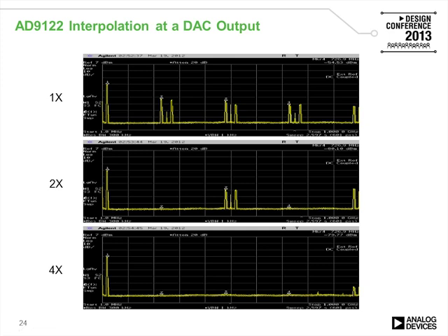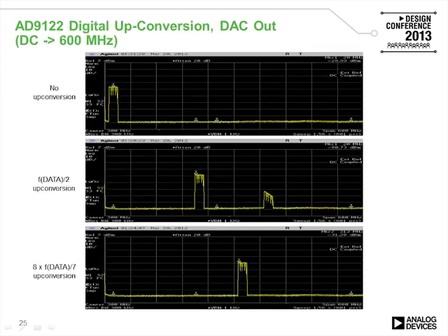One of the benefits of doing this is that our filtering requirements are much sloppier over here when we're doing 4x interpolation as opposed to 1x. If we want to consume this bandwidth right here with 1x interpolation, we would need a much tighter brick wall filter. The tighter requirements mean we need higher order filters than we would when doing a 4x interpolation.